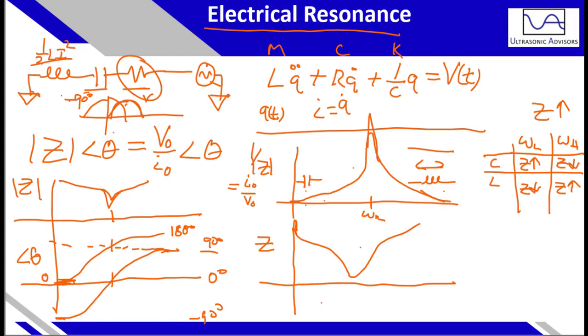And similarly the other way, if you have a higher resistance, you'll have more impedance at resonance, which would also mean a lower current output. So you do have to think about impedance as slightly the inverse of what we traditionally might think of as output, if you're looking at current as your output, which in most devices we do analyze current as a result of voltage.